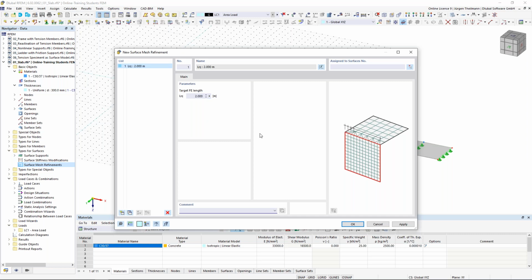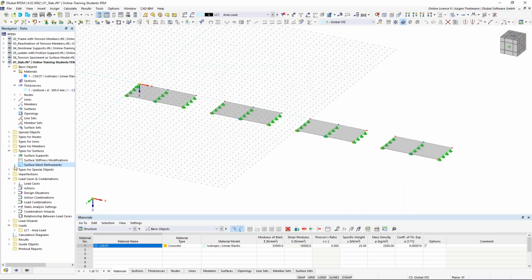I go to apply on the left side, we have this list. On the left bottom, I can add a new mesh refinement. I do this all in the same dialog. So now I set a mesh with a length of 1 meter. Go to apply, new one. And this now can be done really quickly. 0.5 meter, apply, new one, and this one really fine, 10 centimeters, apply.